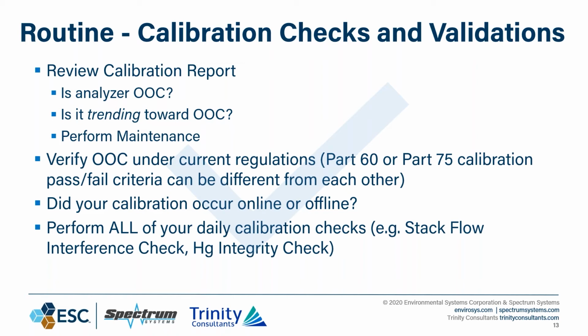of the cal. Are your techs adjusting slope and offset on the analyzer? Are they trying to overcome something? Are they doing maintenance, or are they just trying to make the cal pass? Usually a trend history report can demonstrate what's going on out there.